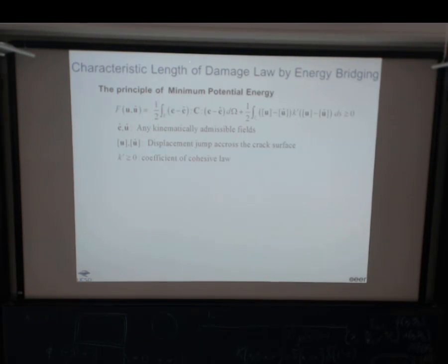Okay, so assume here I have a deformation state E, and that's the deformation in equilibrium. If there's a perturbation, any perturbation from equilibrium, I call it with a hat. Okay, so all the quantities with a hat are the ones perturbed from the equilibrium state. And you can take the difference between these two, and this is a material elasticity tensor, which is positive definite.